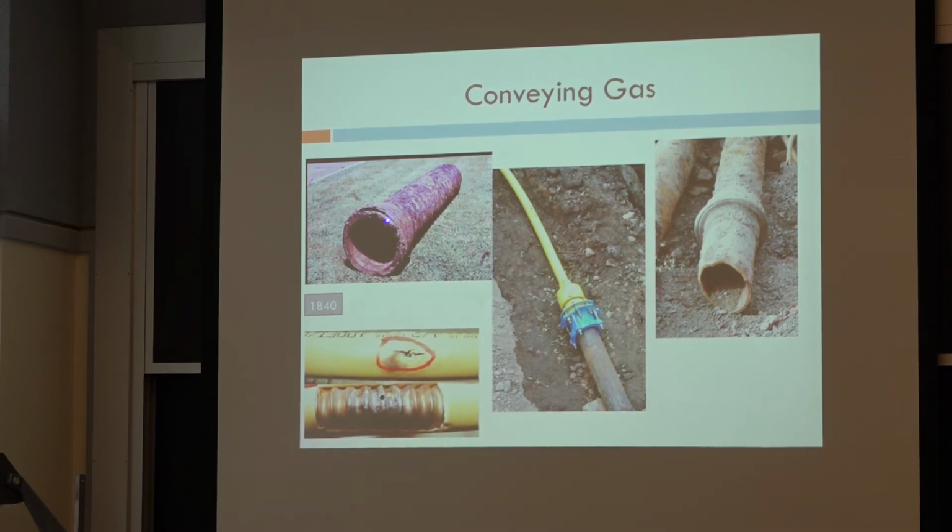But then people realized that wood didn't have a very long lifespan, maybe 20 years, 30 years before it rots. And so people started using cast iron. And we use cast iron for water mains. One of the biggest problems in most of the cities, like Boston and New York, is we've got 100-year-old cast iron water mains, and every now and then one of them breaks. And they're so brittle that when you work on it in this block, you know that about 5 to 10 years down the road, the next block is going to have a leak.